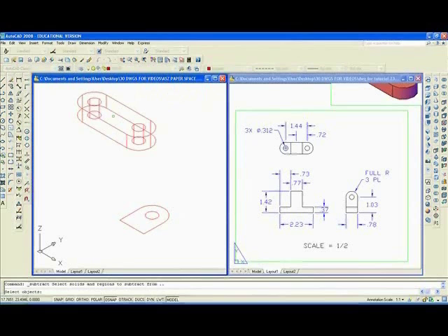Then I'll want to subtract from that, enter, the two holes. Then I'll want to extrude, EXT, enter, this whole area. I'm going to extrude that to a height of 0.77 and subtract from that, enter that, enter.